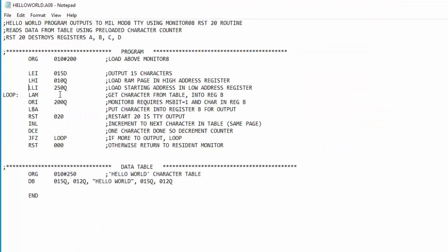There's another little trick we can do, and that is that it's easy to move something and then forget what memory location we put it in. Let's give our table a label. Let's call that table. Now that table has a label that we can reference, so we can reference that program counter, and we're going to use that to put this in for the HL pair.